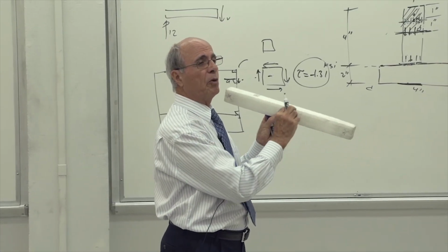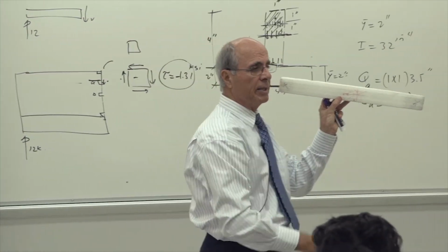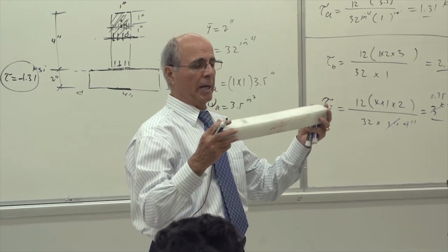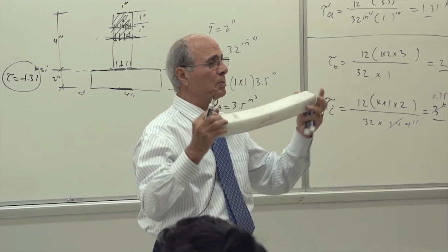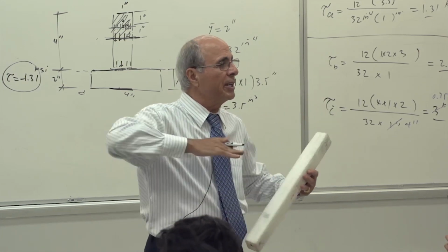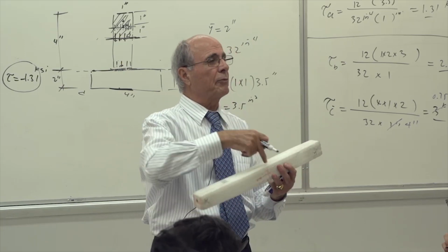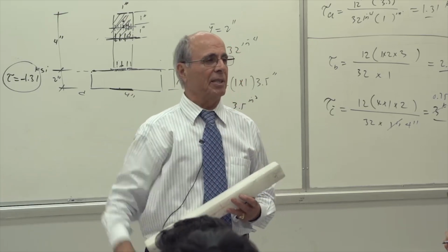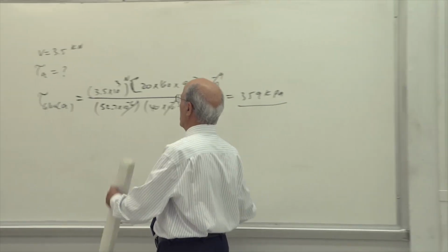Everybody understands. There are 4 different layers put together with glue to make one beam. And if I push it too much in bending, this glue will sometimes come off, because it is under shear stress. So if it is not glued, then I have to nail it, and the nail has a spacing, correct? So let's decide on that first. So glue has gone out.